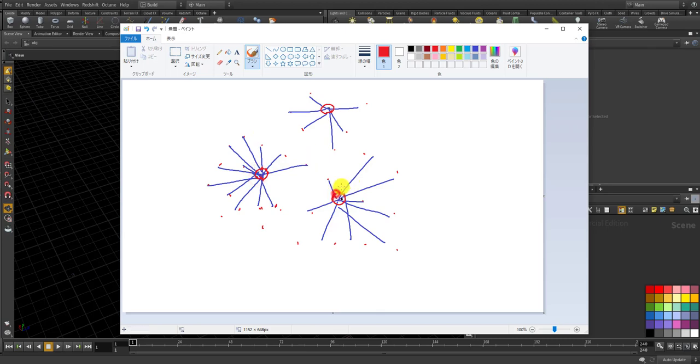And if the closest points on the projected points are too close, it's a bit problematic since you're going to have too many branches from the base points. So use some node like fuse to delete some points based on some limitation, maybe the distance, the radius you set.